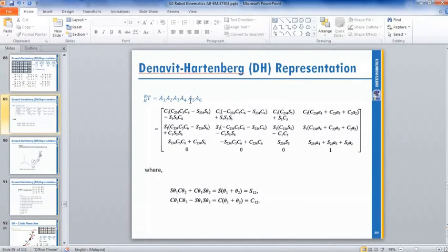Each encoder gives a changing value, so you can define your position in real time, on the spot, instantly. So if you change any theta or alpha between these values, you will get the x, y, z coordinates immediately.